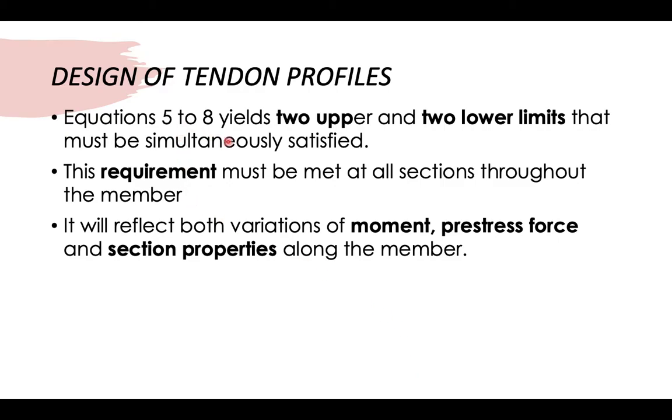Equations 5 to 8 yield two upper and two lower limits that must be simultaneously satisfied. This requirement must be met at all sections throughout the member, so it will reflect the variations of moments, pre-stress forces, and also the section properties along the member.